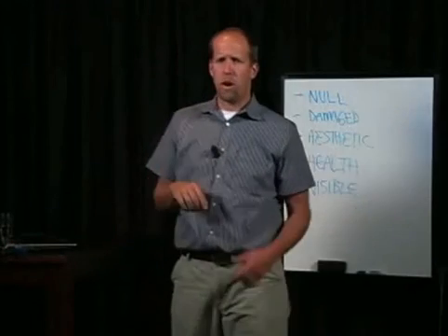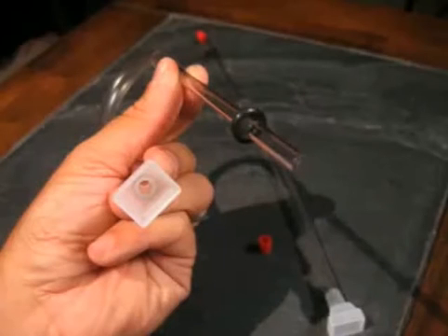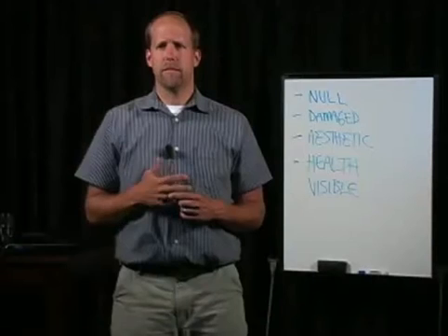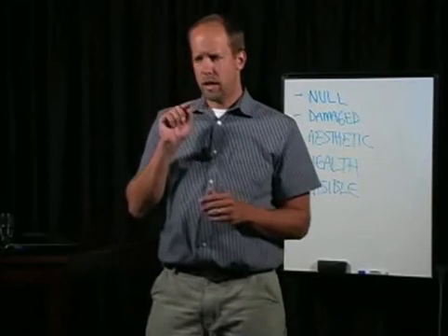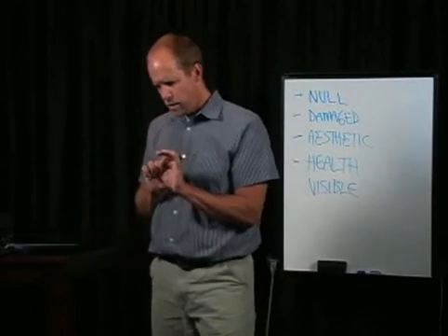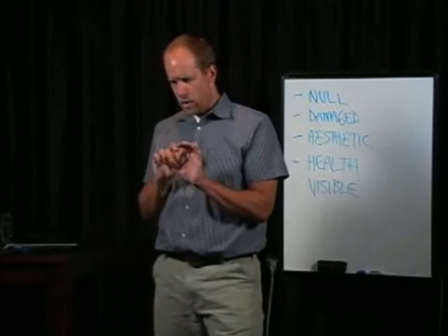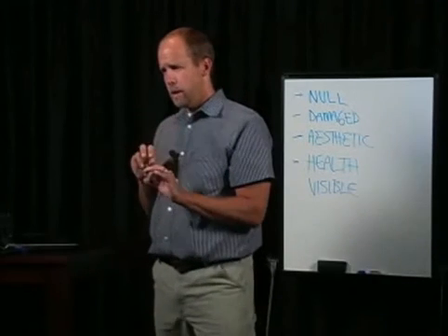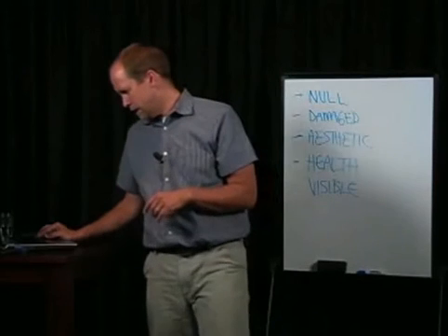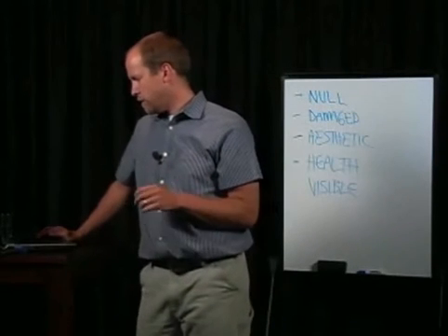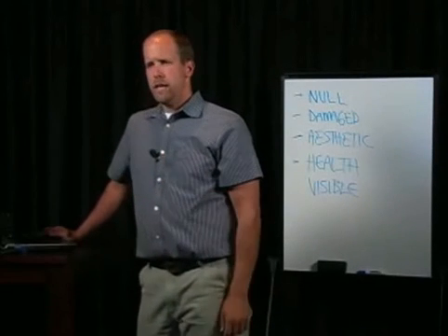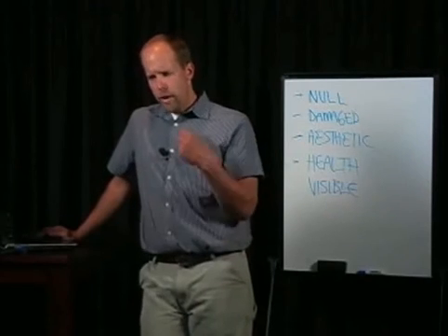There's the wall sampling attachment. This is an aerosol inner wall sampler where you drill a hole very slowly, or you can use a special tool that doesn't make a lot of dust and dirt. Stick the instrument in. This is an invasive, destructive instrument that takes air samples from a wall cavity.